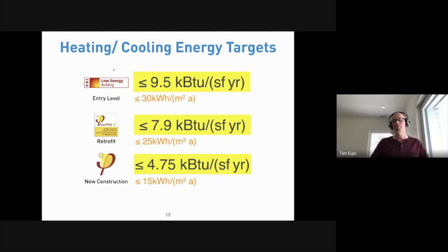The retrofit program is wonderful, and that is also something where the Passive House Institute is still one of the few outfits that provides a clear retrofit path and program. 25 kilowatt hours per square meter a year. There's some other parameters around that, and I should say we won't go deep on that today, but they have different retrofit tracks. There's component-based, there's building-based, and there's also phased retrofit. All of these are in recognition of the challenges of retrofitting the built environment. And so as far as that goes, it's a fairly mature and really great program.